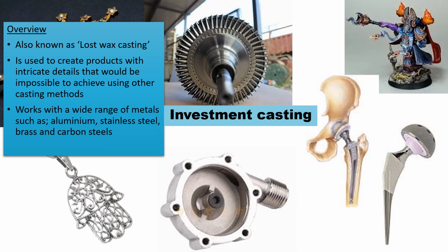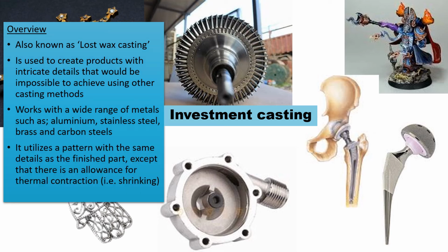It works with a wide range of materials, or metals rather, such as aluminium, stainless steel, brass, and carbon steels. And it utilizes a pattern with the same details as the finished part, except that there is an allowance for thermal contraction, so it will shrink ever so slightly.